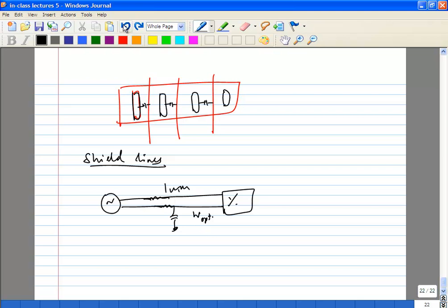Okay, now the next question is, if they're going from the VCO to the divider, they're going to be very sensitive lines. Do you want to add a shield for them? So let us say you add a shield on both sides. Okay. What happens? So now you have some extra capacitance to the shield apart from the substrate. You have the capacitance to substrate already, and you are basically adding extra capacitance. Okay. So now you need to space them out wider.